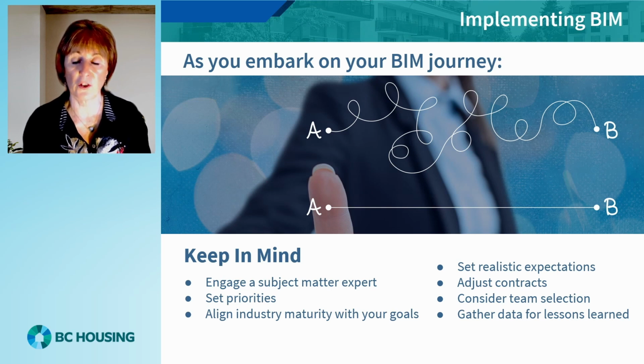Consider carefully the contract type being proposed. Remember, to be successful, everyone is using and building on the data being generated in an iterative manner. BIM is a collaborative process, so it works best with a collaborative contract form, where the owner is actively involved. When choosing the team during the RFP, include BIM in the assessment criteria, along with attitude and BIM maturity. These things matter. Finally, it's vital to keep a lessons learned log and feed back into the initial BIM requirements.